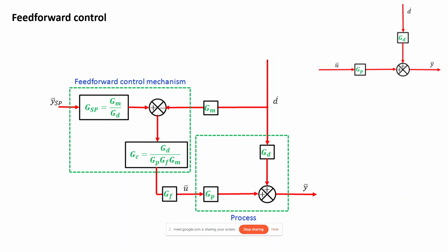So as mentioned earlier, in a feed forward control system, we won't be measuring the output, but we will be measuring the disturbance of the system. So this is what this block diagram shows. I am having a disturbance as an input to the system. Then I am measuring the disturbance by using a transfer function of GM, that is the measuring element. Then correspondingly, we will be taking a controller action using this final control element and change the manipulated input to the system by calculating this YSP.